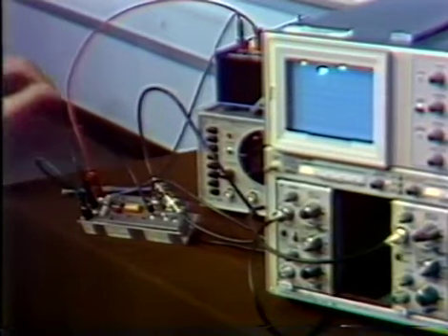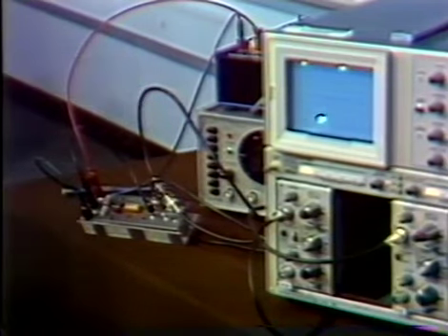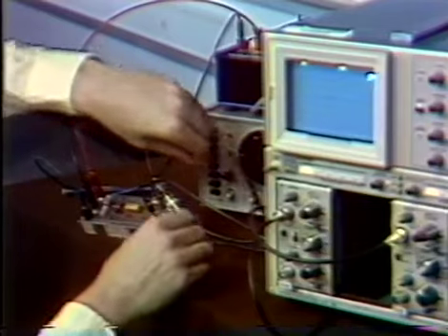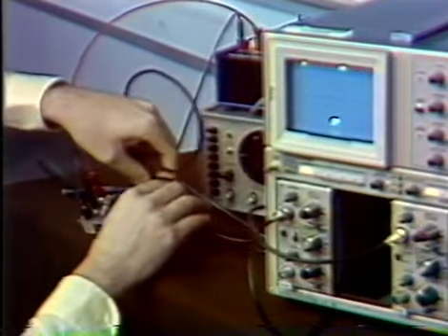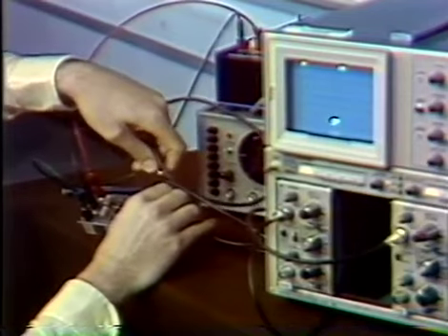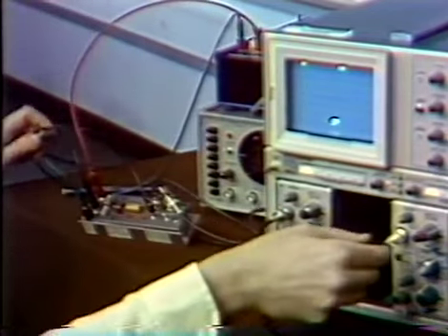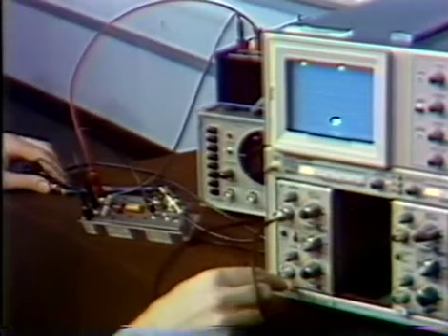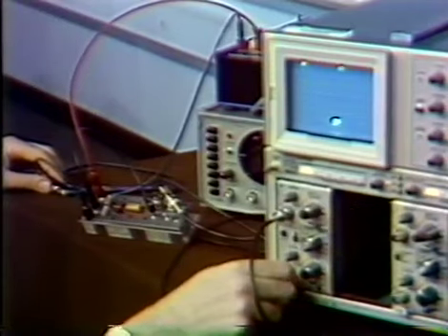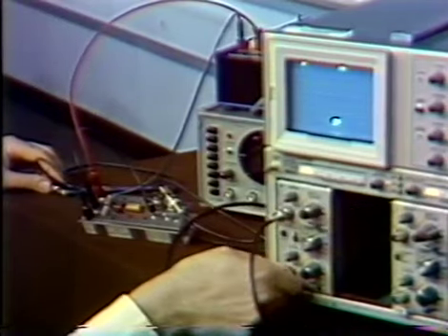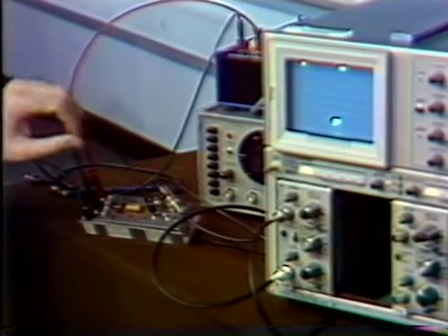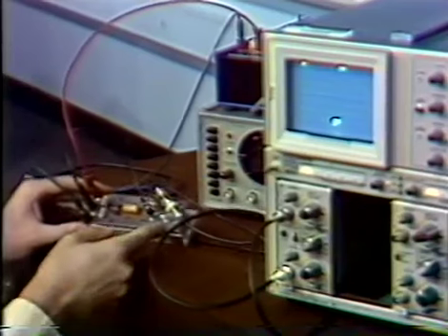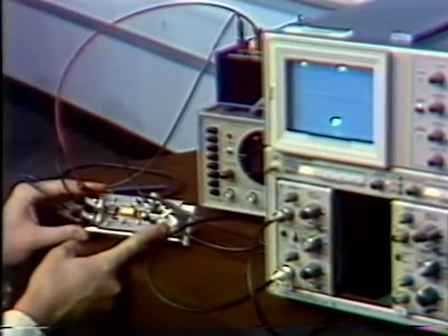Now let's complete the loop and look at some of the signals. First, I'll disable the function generator, the external one that we were driving the system with, and I'll apply that signal to a second axis on the oscilloscope. This is actually now the input signal to the Schmitt trigger, or equivalently the output of the integrator once we close the loop. This switch simply closes the loop.